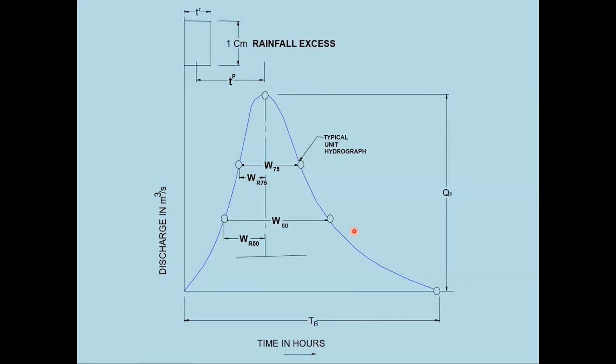In case I find that this hydrograph is showing me excess discharge, so I want to make it lower. So what I will do, I will draw the curve going like this. So the area will decrease. If I find that the discharge is coming less, so I have to increase the area, but this and this point are fixed.